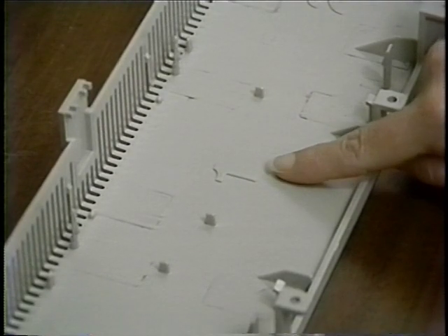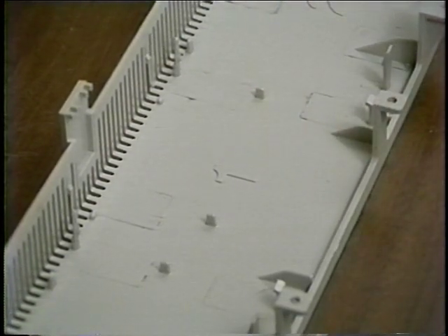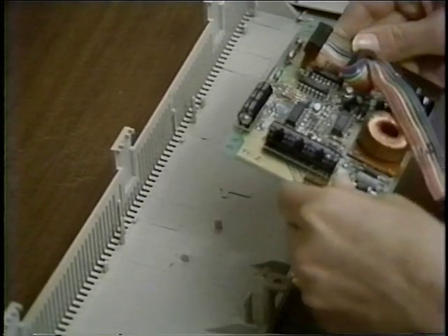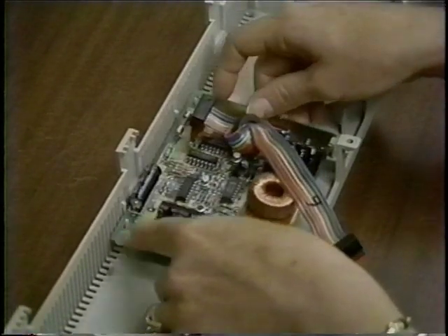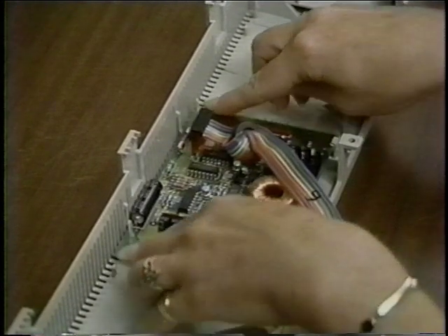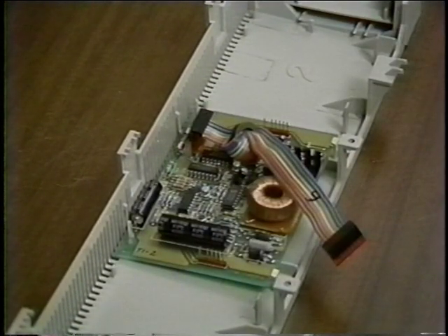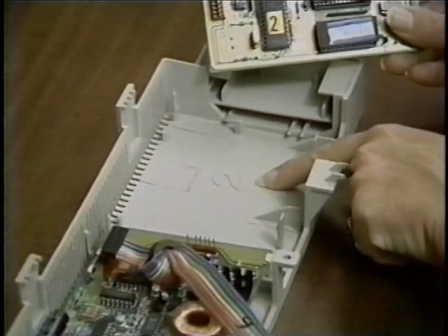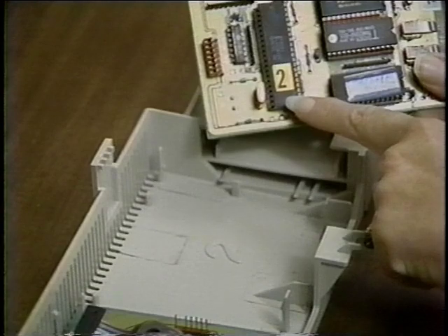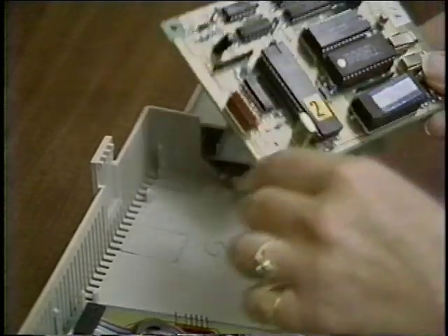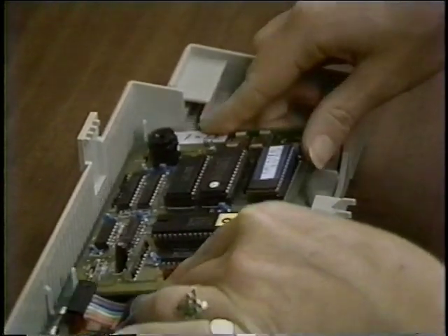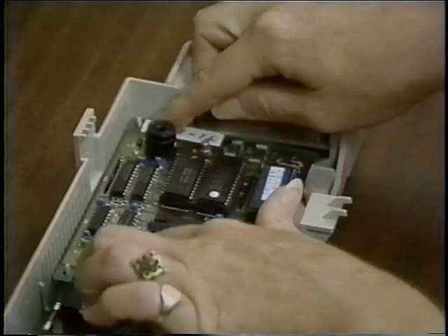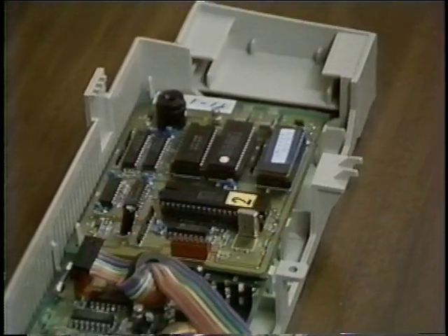To install the features adapter board, place the front edge of the board under the latches in the area marked 1. Then align the mounting holes in the top of the board with the mounting posts. Press down on the board until it latches under the retaining clips. To install the spelling verification board, which is board number 2 in the option cover, place it in the side marked 2. Align it so the mounting posts fit through the mounting holes in the board, then press down on each corner of the board to latch the board in place.